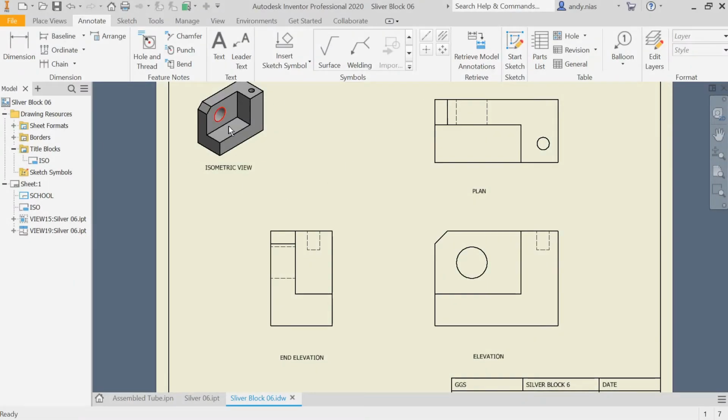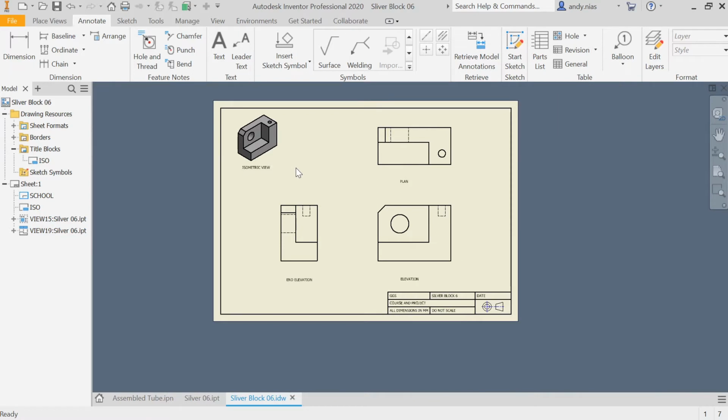Okay, so now we're ready to add some dimensions to our drawings and centre lines. You may notice that I just added an extra hole here on the part, and you'll see why that shortly. So first off, dimensions, very simple. We're going to pick up the dimension tool here. There are other options, but we'll not really run with them for now.